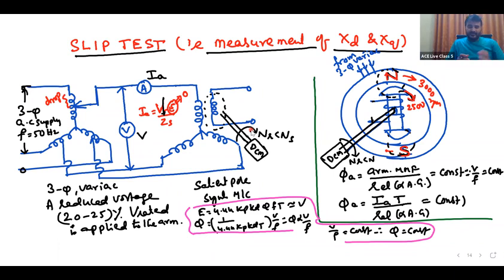The reason is that the phase sequence is not proper. Say your rotor is rotating clockwise, but if the phase sequence of your supply is not the same, the armature poles may rotate in the opposite direction, say 3000 RPM counterclockwise. The rotor is clockwise, the armature poles phase sequence is different, so both will rotate in opposite directions. Relative speed is nearly double the synchronous speed, then the induced EMF is very large, at nearly double the supply frequency.